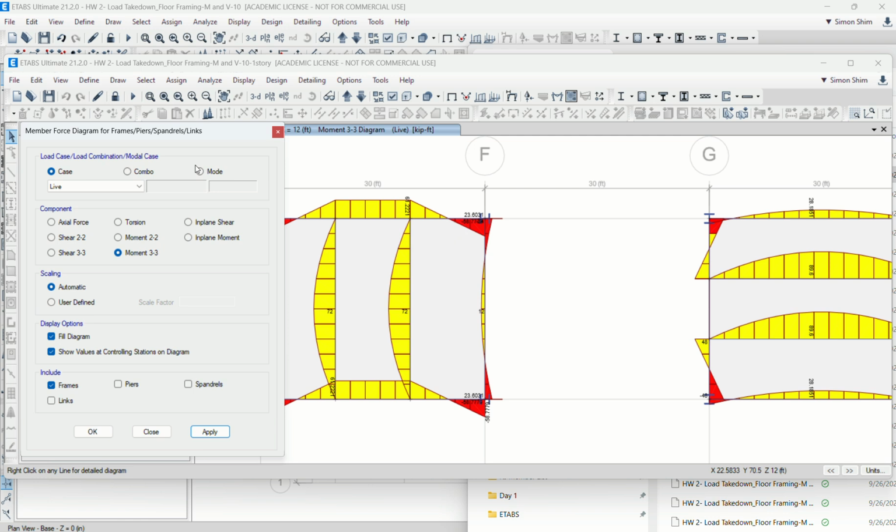But I had to, using my engineering judgment, understand what is up there, the material on the roof, what the beam size is, that it's wood, and what the weight of the wood is. Depending on the wood species, the weight is substantially different, right? Especially with old pine, southern pine versus white pine, their weight is almost 50% different.